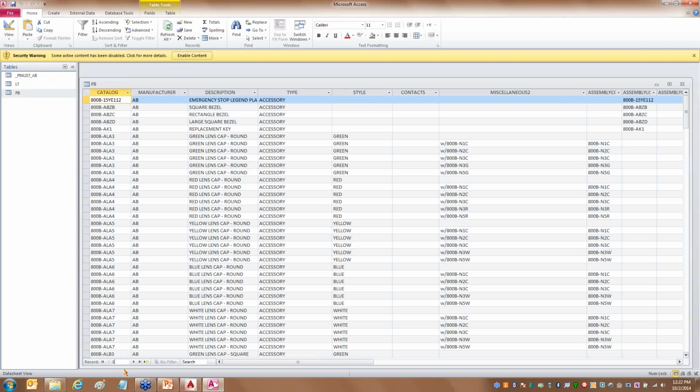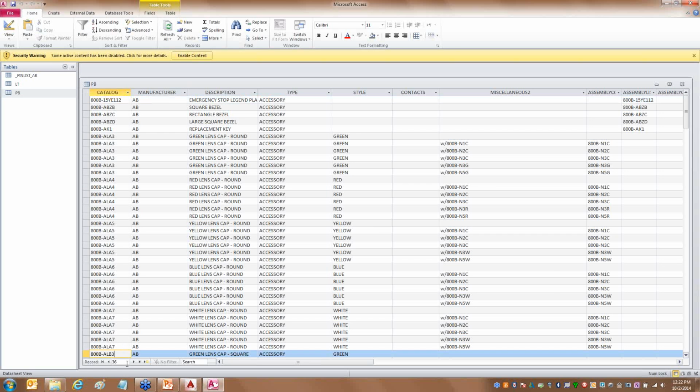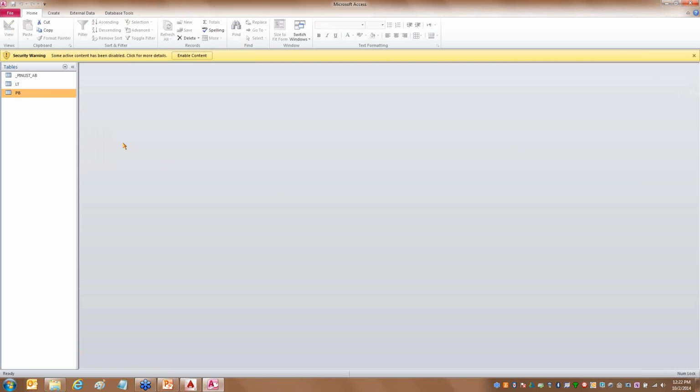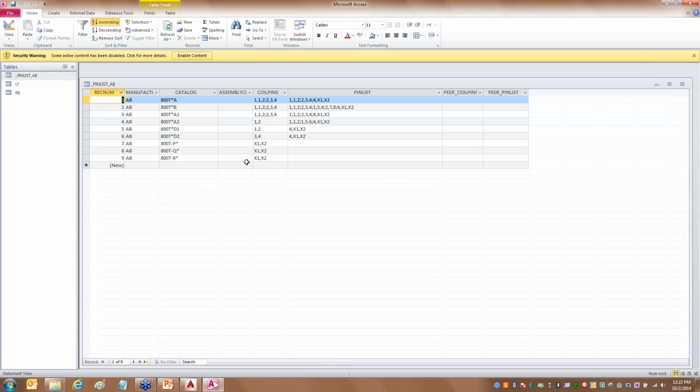But just to show you, it's the same exact catalog. If I come down here, it should tell me in a second that it's 54,117 push buttons. Exact copy. Nothing's changed from that default catalog. Where I have made changes is right here in this pin list for Allen Bradley. And I've gotten rid of everything in this pin list except for what I want to migrate.